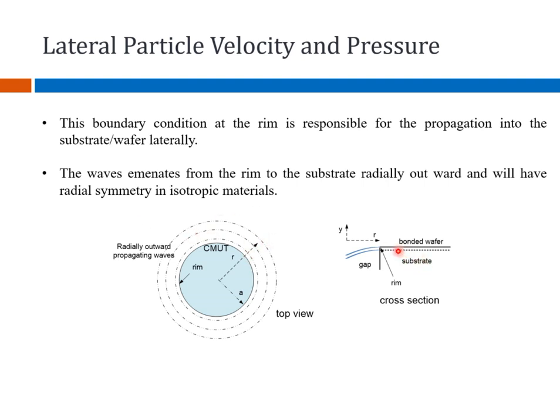Okay, so the point where it happens is the point where the bonded silicon plate with the glass is fixed. Okay, it is fixed at the rim. So it's just like if you can think of this as a springboard. I mean, if someone jumps off it, right, off in the swimming pool, let's say, so it's a pad which is going to vibrate, then this vibration is going to be countered by, since it is attached to the rim, it is clamped to the rim. The clamp conditions are different over there, but still those vibrations are going to be counterbalanced by the backing, which has a different wave impedance, right?